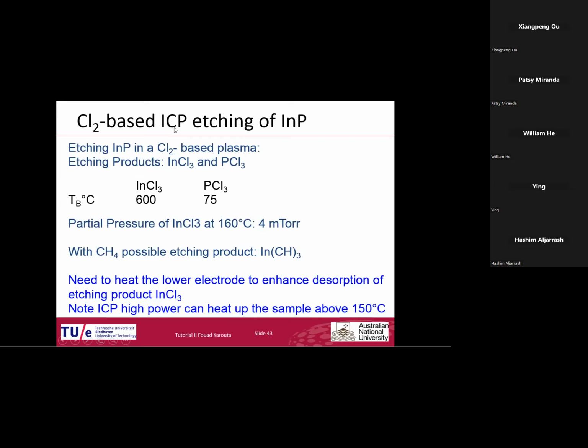I did some etching in ICP with chlorine of indium phosphide. And as I said, we had to go at higher temperature at pressure about 4 millitorr.